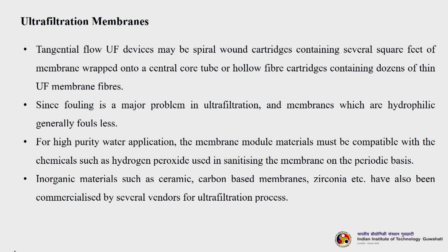Inorganic membrane materials such as ceramic, carbon based membranes, zirconia etc. have also been commercialized by several vendors for ultrafiltration applications. We just discussed the disadvantages of having ceramic membranes, but there are plenty of advantages also.